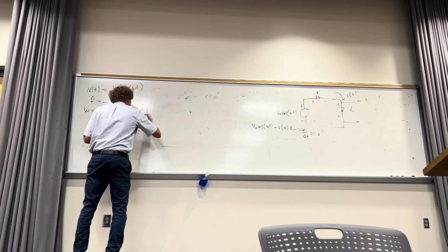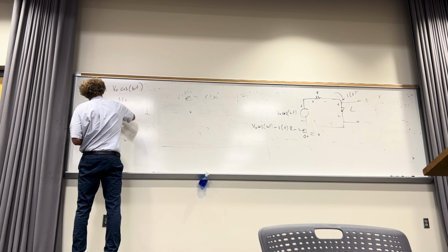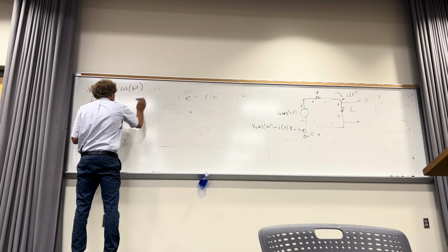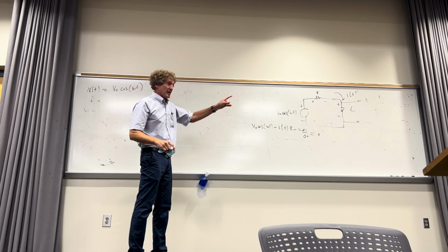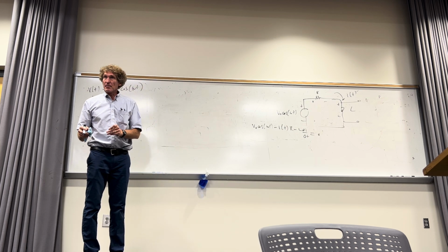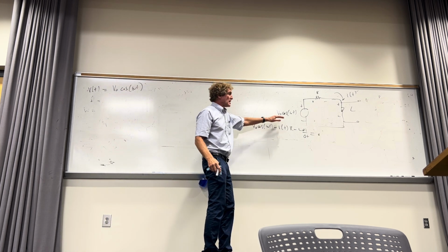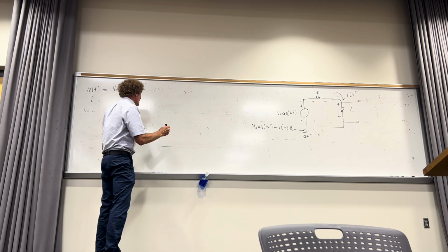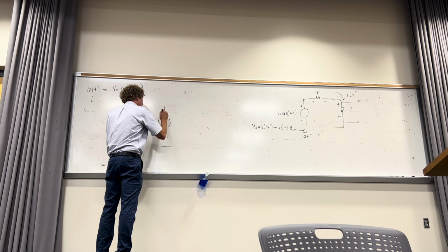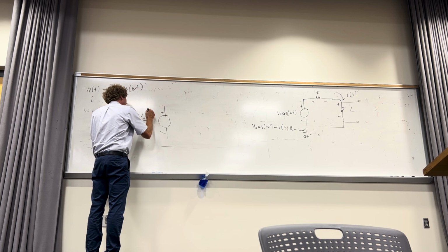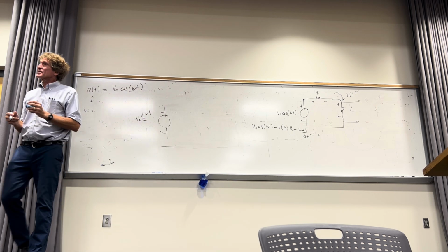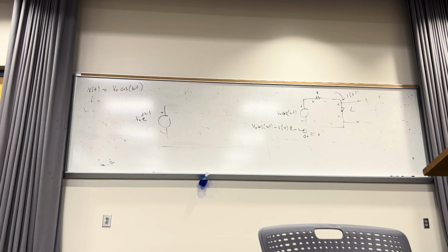So now we do this. Let me get rid of this too. I'm not trying to make this stuff difficult or confusing, or in any way overlook a step. Here's that circuit. Here's how we solve it now. Instead of putting this in, and it even gets easier in a second, we replace that source by just V naught e to the j omega t. Are you with me? I know that has that j term in there. Don't worry, when we get done with everything, we're only going to take the real parts of both current and voltage. You with me, class?